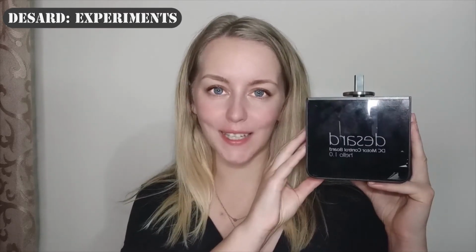What does this box have inside? It has a DC motor and an encoder. Why do we need an encoder, you will ask? Well, if you want to measure how many turns your motor makes in 1 second, you need an encoder for this. This part does the job. After that, we convert this value into RPM, which is more natural for us to interpret.